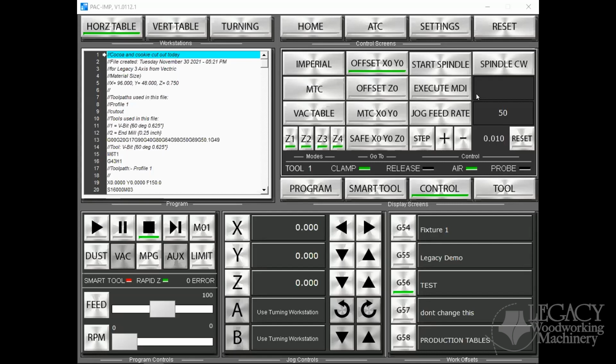So we can just go to the XY0, it'll be at the Safe Z at the top. And then we can click on this button to go down to the Z to check it if you want to do that. And since I just set it, I knew it was perfect. So I had the courage to click that button and then it was okay, right?